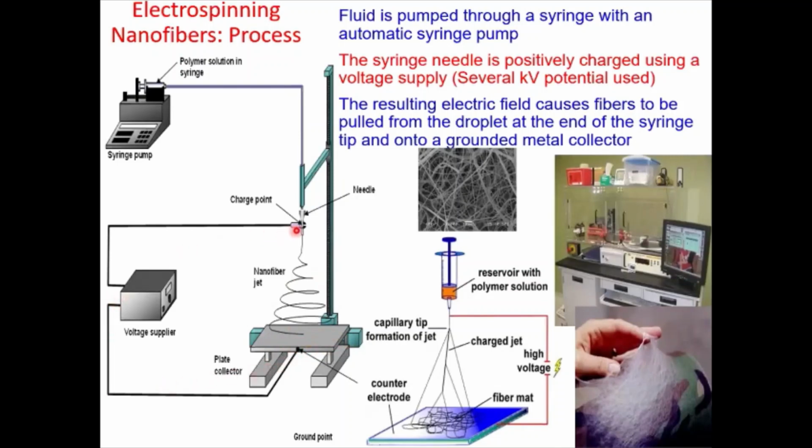So you have a power supply connected to the needle as well as the collector, and then the syringe is filled with polymeric solution, and the syringe movement is controlled with a controller, right? You can make the syringe a reservoir and push the polymeric solution slowly depending on the movement or control of the controller. You can spray very fast or slow through the needle using this controller, right?